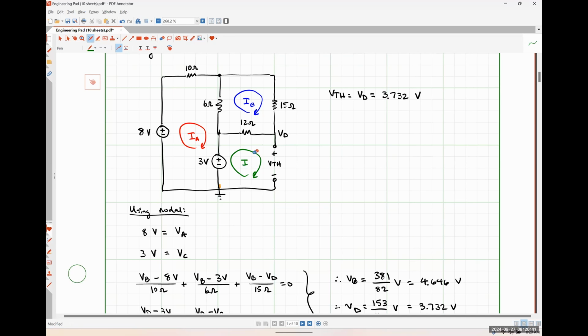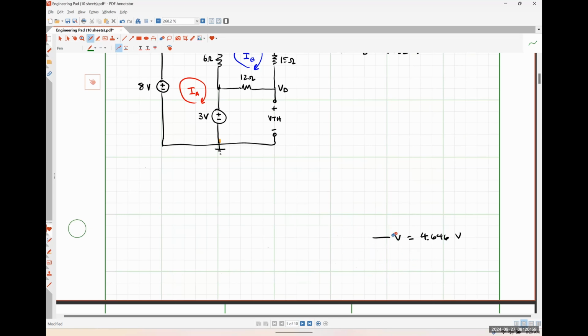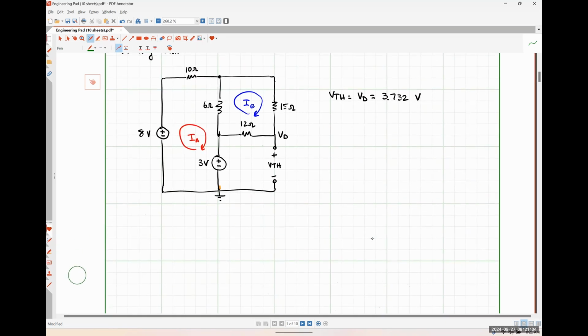Okay. So I'm going to erase that guy. Let's erase all this jazz down here because we're no longer doing nodal analysis and just see what shakes out. So we have identified our meshes. We have assigned our mesh currents. There are no controlling variables. There are no current sources. So all we have to do is apply our KVL equations here, right?